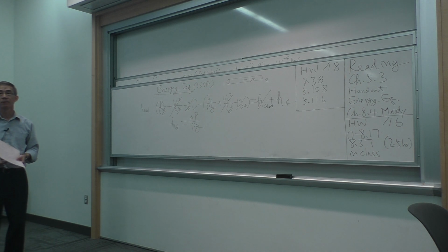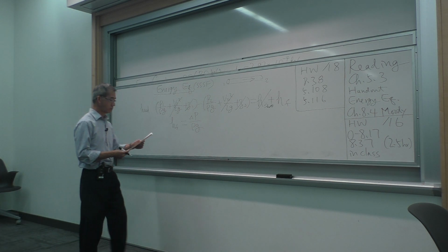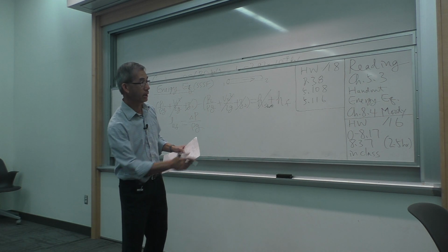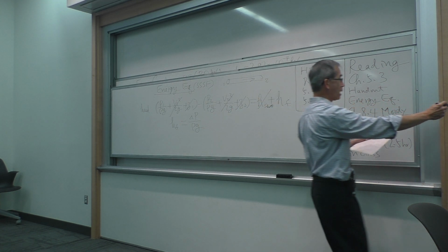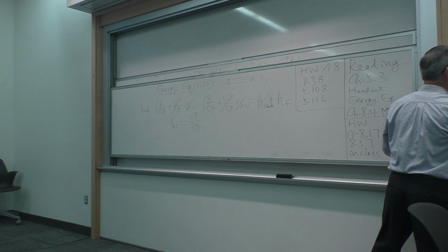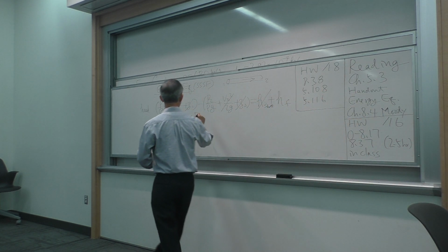So that's 7 liters of water. It just translates to how many kilopascal of pressure drop due to friction, rho g h. And my pump better provide enough pressure-wise to overcome that delta P in terms of kilopascal, or the flow is not going to go. All right? So dimensional analysis, which is halfway here. Now I'm going to replace this delta P with the delta P in here.